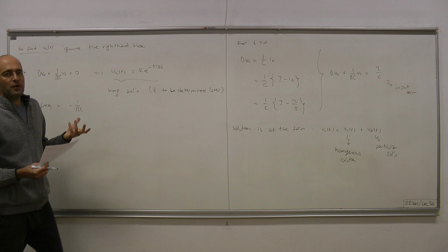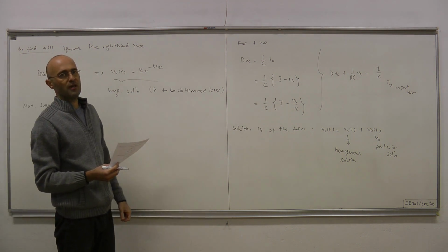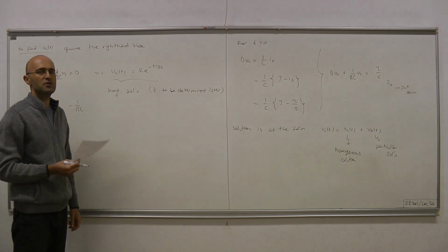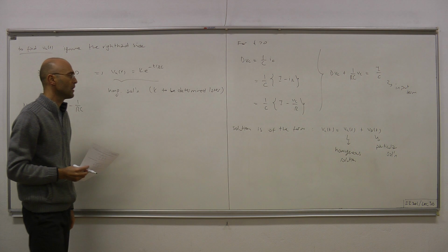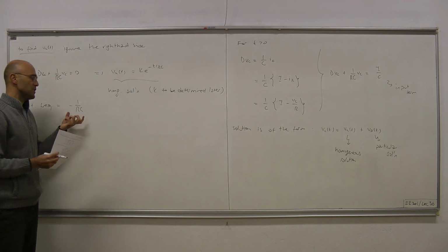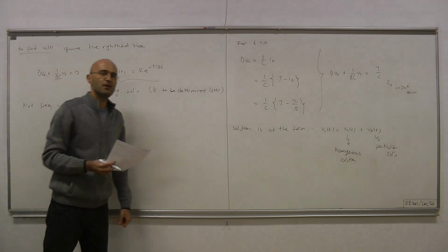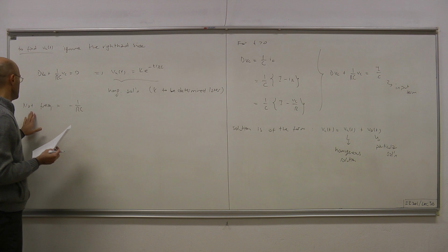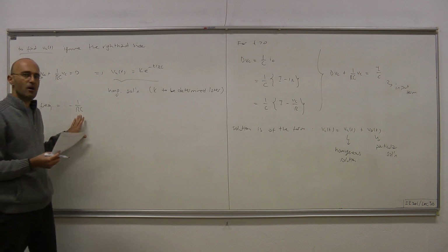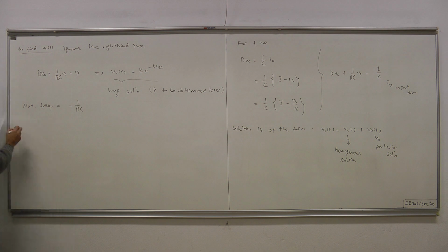If you have an arbitrary dynamic LTI circuit, you can kill all the sources within that circuit and obtain the differential equation describing some variable, capacitor voltage or inductor current. And then the natural frequencies coming from that equation are the natural frequencies of the circuit. And by definition, the time constant is RC.